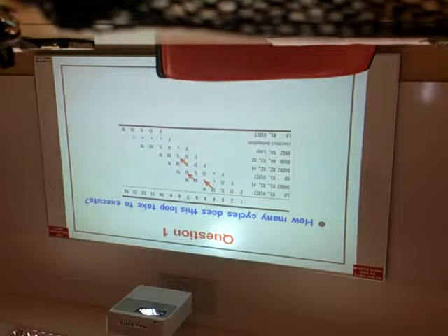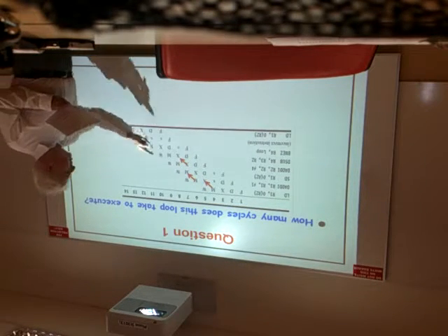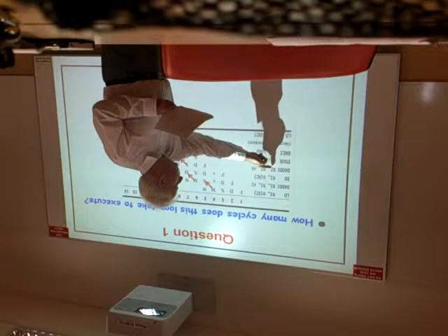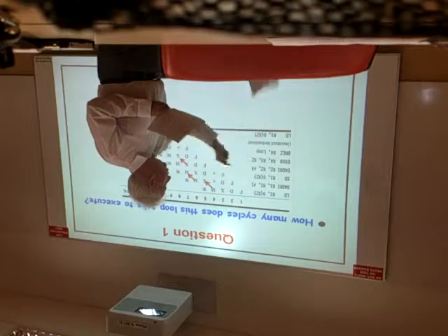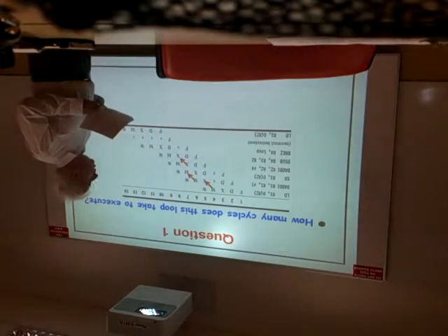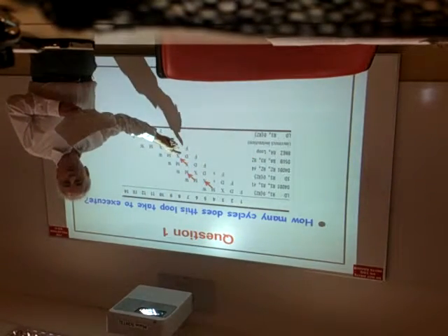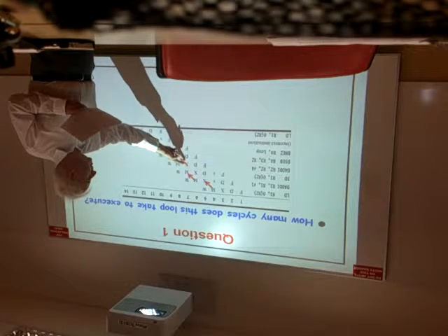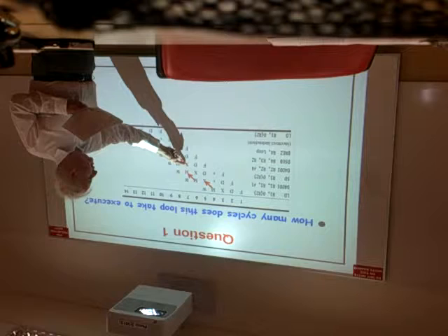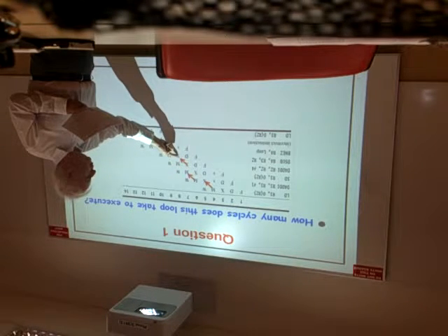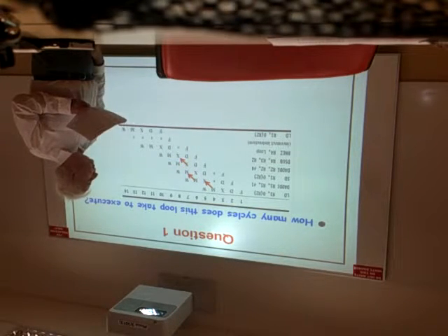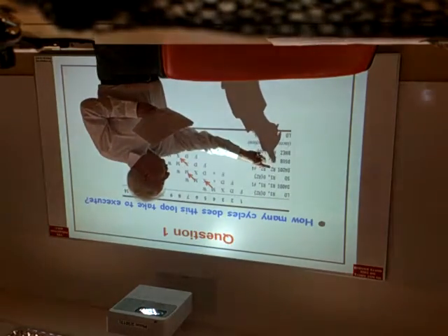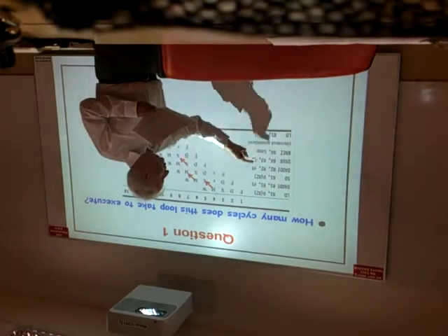Again, we have a read after write dependency. The value of R2 is calculated here and used in the next instruction. Here, in fact, we don't need a stall because we can simply forward the data from the execute stage of this instruction to the execute stage of the next instruction. So the execute stage calculates R2, and we forward it to the execute stage of the next instruction.